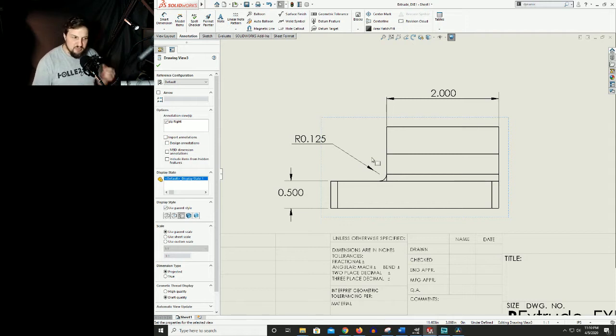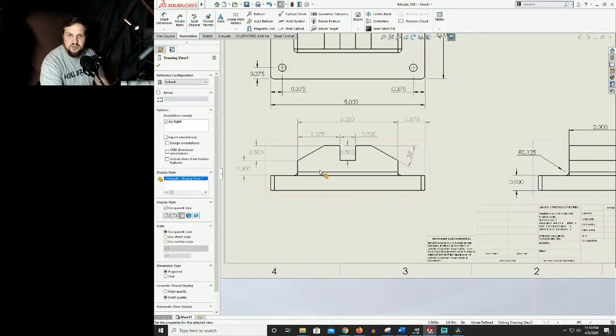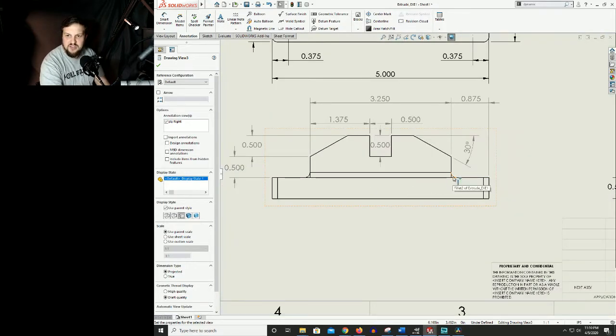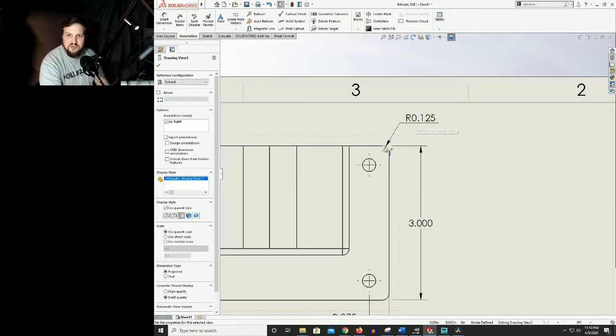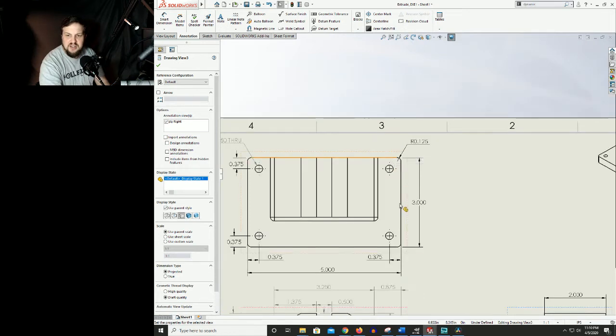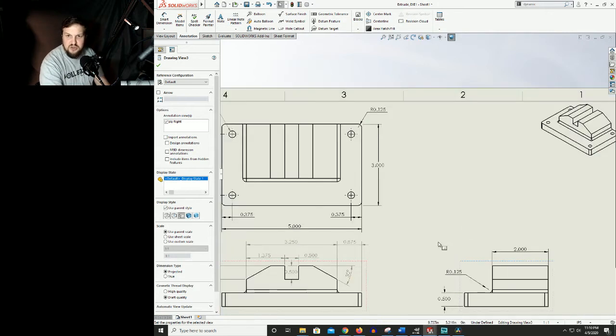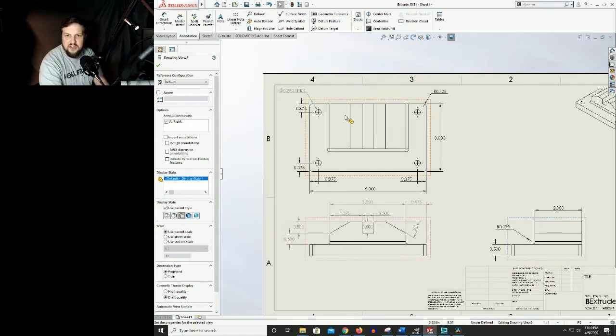And again, we want to remove the assumption process in these. So, for instance, what I mean is we've got this radius right here. Okay, and this radius right here is attached to the same edges that this radius and this radius are on. Likewise, this up here, this 0.125 radius, is attached to this one, but maybe not all 4 of those. And what does the end user know as far as that goes? We've also got our 0.375s here, here, here, and here.